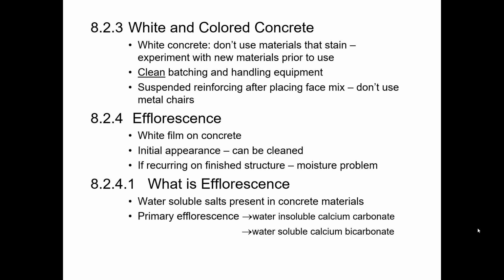The difference between primary and secondary is that primary is happening with the water that was present because of the concrete production process. So the water that was present on and in the aggregates, as well as the mixing water, as that piece continues to dry out and cure over a period of months, that water is all slowly but surely making its way to the surface. And you might start to see that primary efflorescence show up even while panels are stored in your storage yard.